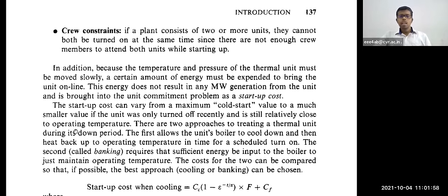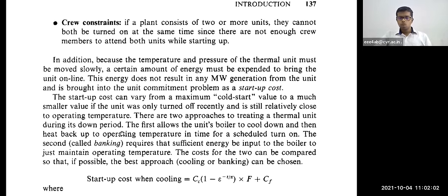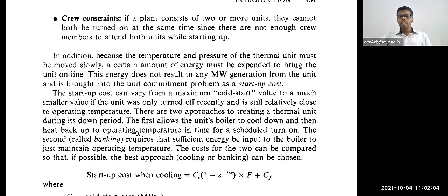So another concept is called cooling and banking. Cooling and banking: first, cooling allows the unit boiler to cool down. After the unit is running, what they will do is let the boiler cool down, then heat back to the operating temperature in time for the scheduled turn on.